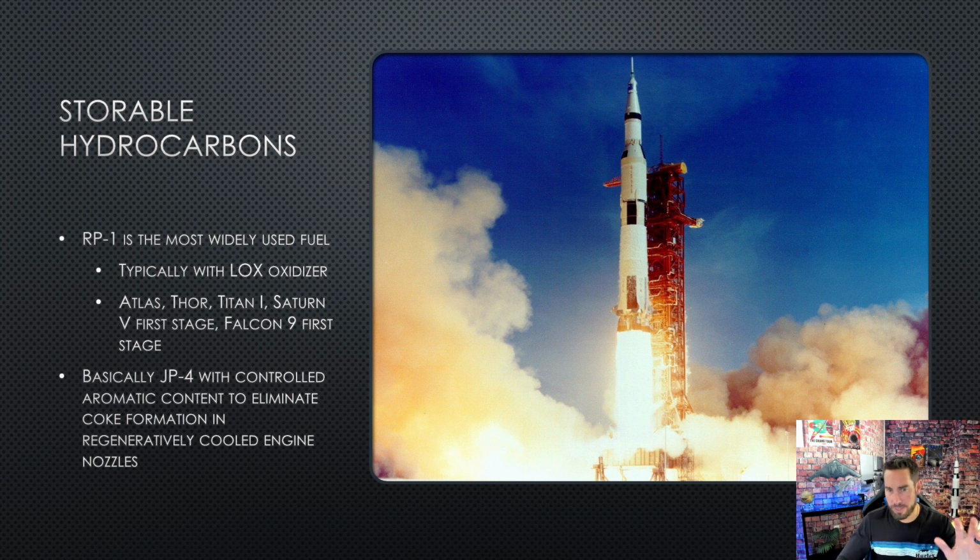And actually kind of a cool thing, if you see a rocket with a bright plume like this coming out, it tells you pretty much right away that it's RP1 plus liquid oxygen. Basically you get unreacted carbon that gets into the exhaust stream, it reacts, and you get this really bright glow that comes out of it. Rockets that have, I'm not going to call it an invisible flame, but a much lighter flame, you can actually see the shock diamonds that are forming in it.